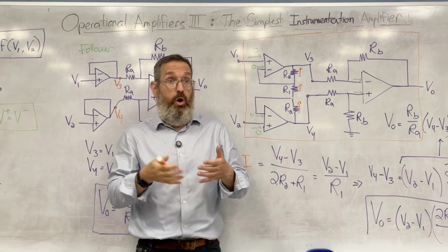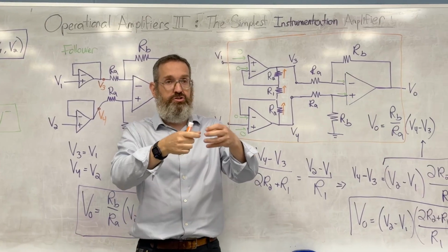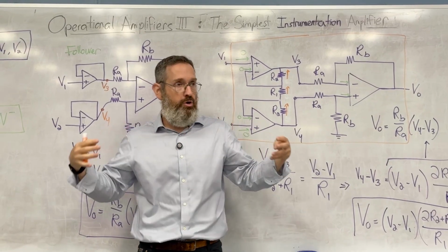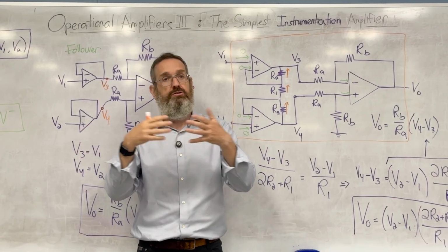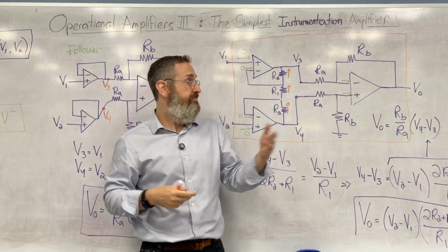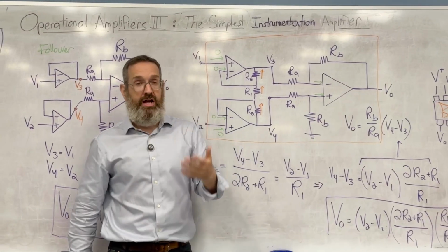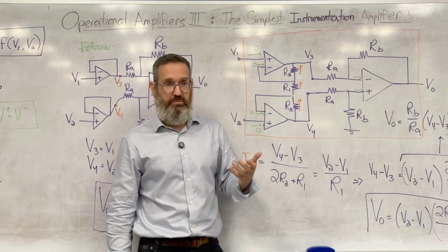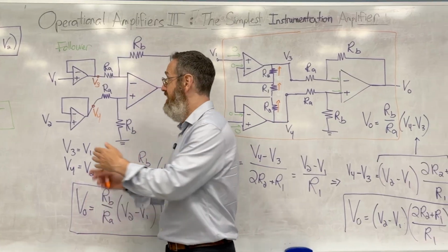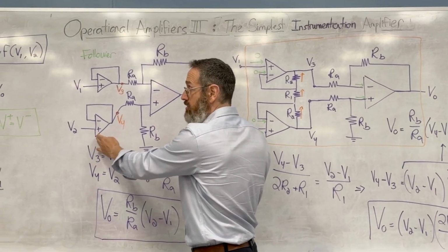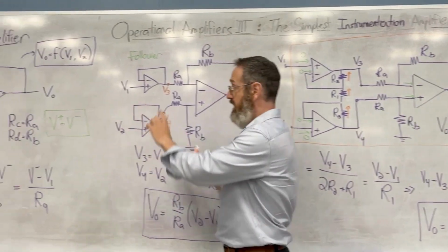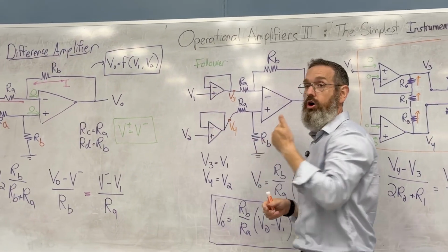And if I could say one option is you build a circuit with 3 op amps, power all of them, connect all of them up, don't make any mistakes, or use a single chip that has 3 op amps in it, you would rationally want to use one chip, right? And so we get all this, right, which has a benefit that that doesn't have, right, because it has these buffers in the beginning, on one chip.